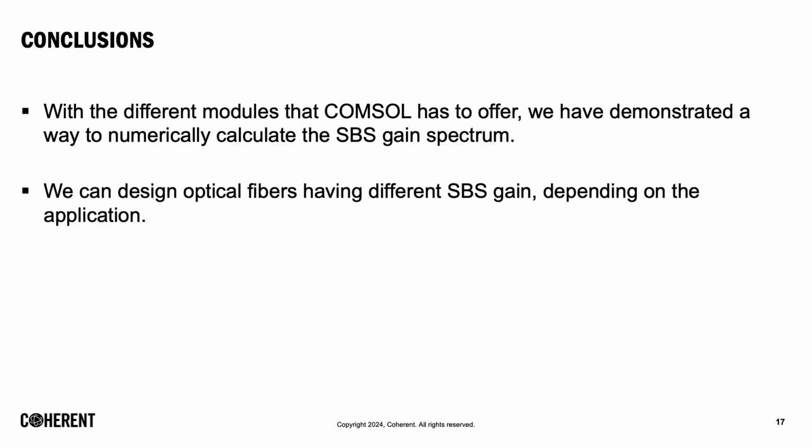As a conclusion, with all the COMSOL models available, we have demonstrated a way to numerically calculate the SBS gain spectrum using a combination of the COMSOL models acoustics, wave optics, and LiveLink in our case. We can design optical fiber having SBS gain depending on the application. In fact, we have the capabilities in Coherent to design different optical fibers depending on the SBS gain level that we want. And with this, I would like to finalize my presentation.